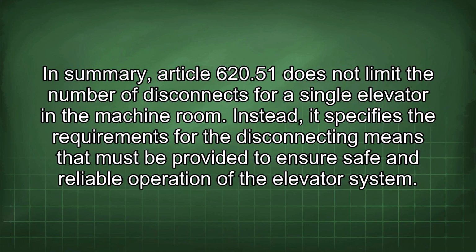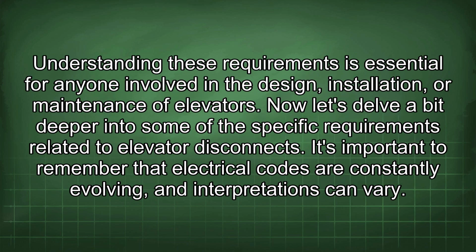In summary, Article 620.51 does not limit the number of disconnects for a single elevator in the machine room. Instead, it specifies the requirements for the disconnecting means that must be provided to ensure safe and reliable operation of the elevator system. Understanding these requirements is essential for anyone involved in the design, installation, or maintenance of elevators.